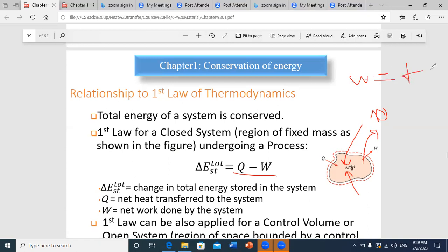But when you go to the energy balance, you will say that delta E is Q minus W. So when you apply it here, you will do minus 10. At the end, it will be accounted as a flux leaving the system, so it's minus 10.